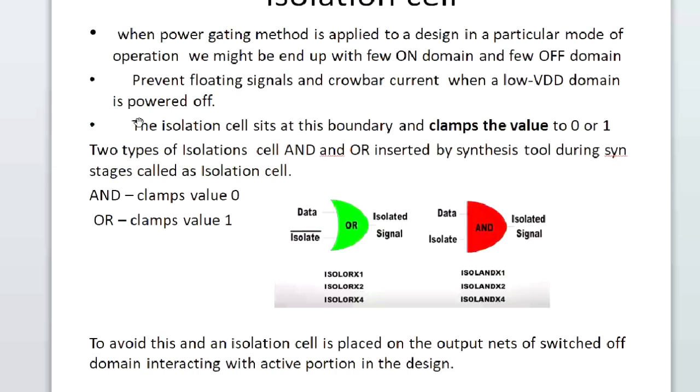For example, a CPU or GPU works at high frequency in chips, so they use high power domains like VDD1, and some go into a low power domain where only a single VDD is enough. So basically, we are going for multi-voltage, meaning more than two VDDs, and for the other case we can say one VDD. Based upon that, we are initiating the design.